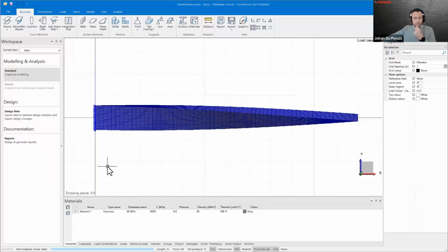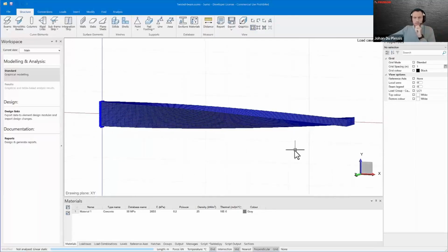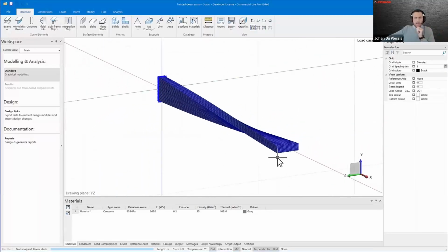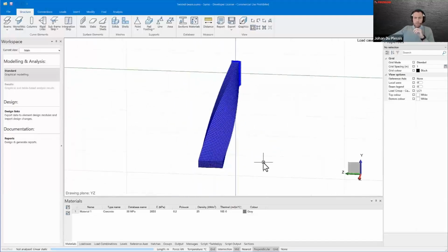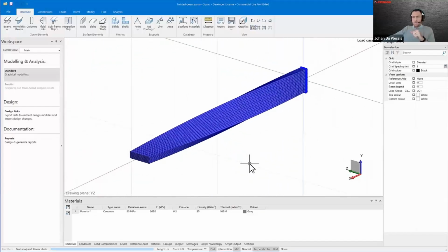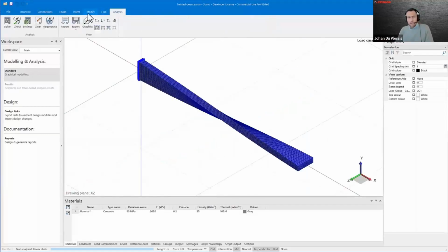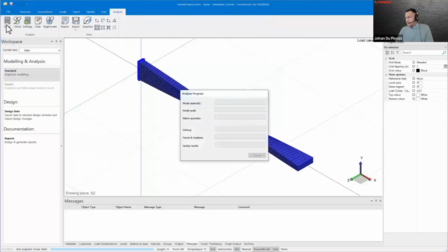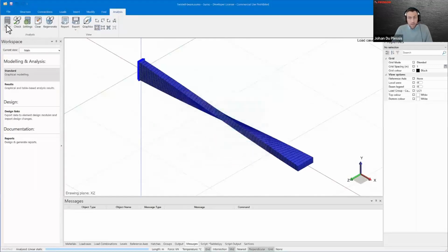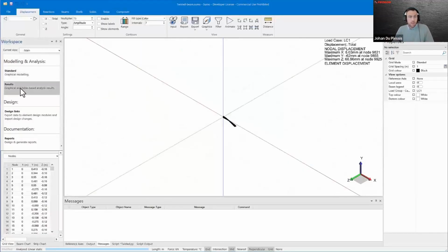As you can see, the material I have here is just a normal concrete with a 26 GPa Young's modulus and a Poisson's ratio of 0.2, so fairly standard properties there. And I've modeled this twisted geometry using the shell elements. Now you'll see that the analysis takes a few moments longer than usual, because there are 8,195 finite elements that I've included here. So you can imagine how many more degrees of freedom must be solved.